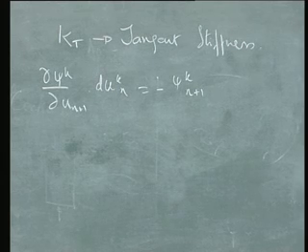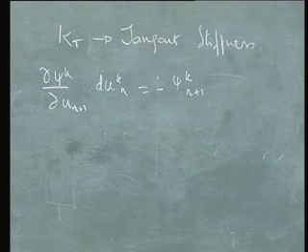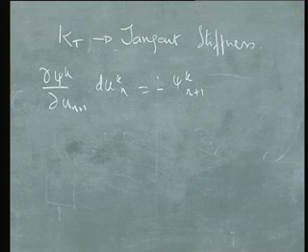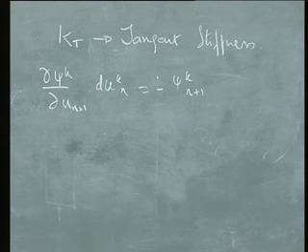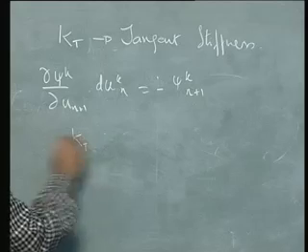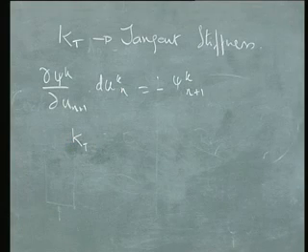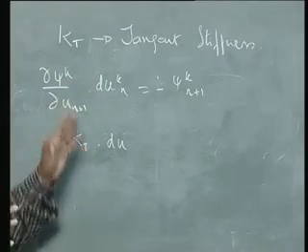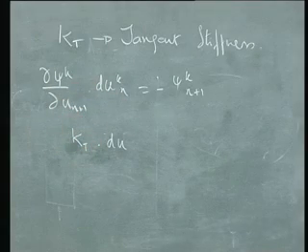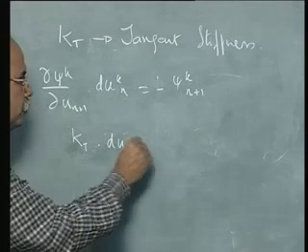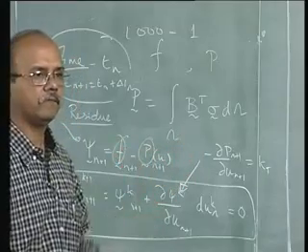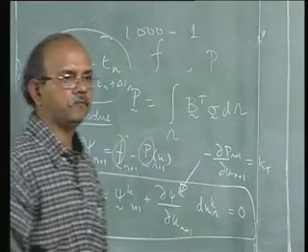Tangent stiffness matrix. Okay, and that when substituted back into that equation gives rise to what? This equation, when you substitute it here, gives rise to an equation of the form Kt du. Let me remove all these things for clarity. You can put it back again. Kt du is equal to psi, that is P minus F. Okay, P minus F.